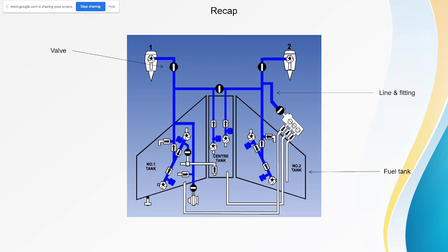Next, the flow is driven by pumps that are installed at the end of the fitting and line. If you notice, there are also pumps at the engine. They are called engine-driven pumps, while the pumps at the tanks are called booster pumps. During flight, both pumps operate, with the engine-driven pumps sucking the fuel, and the booster pumps helping to ensure positive fuel feed to the engine.